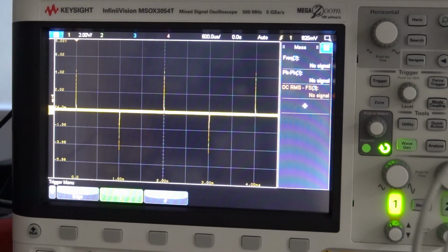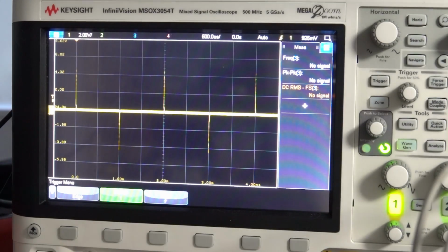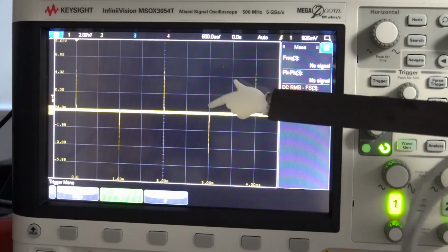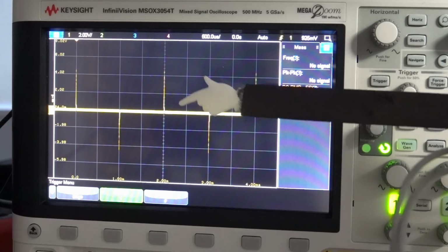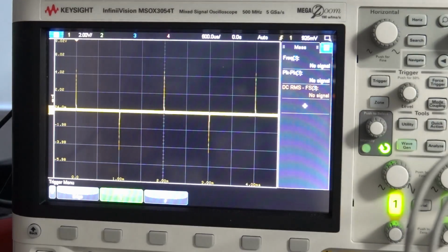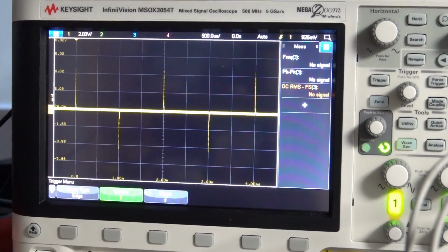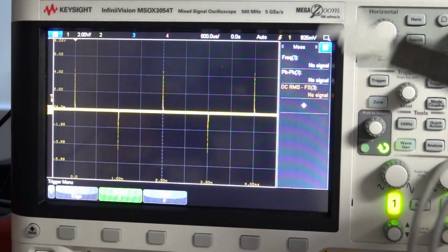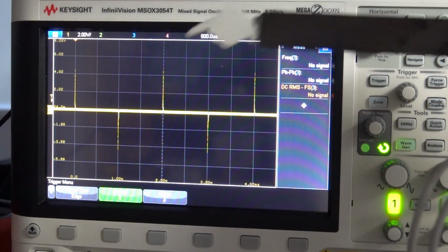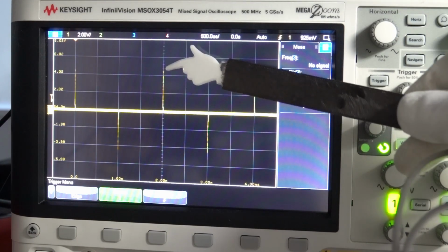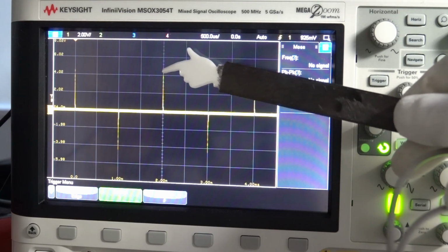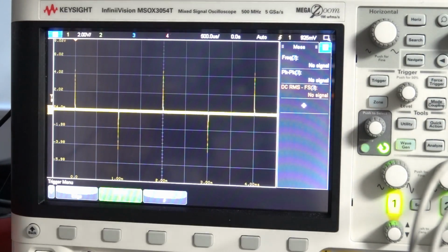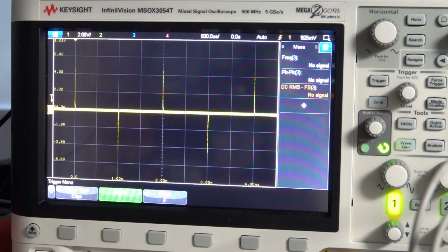If we increase the frequency to, let's say, 500 Hz, we see many more spikes. 500 Hz, by the way, is the PWM frequency of the Arduino. Because of our 1 kilo ohm resistor, 1 volt on the screen is equal to 1 milliampere. Peak current for the moment is more than 4 milliampere. Not nothing compared with the theory. This is why it's good practice to add a resistor in front of the gate to protect your MCU pins